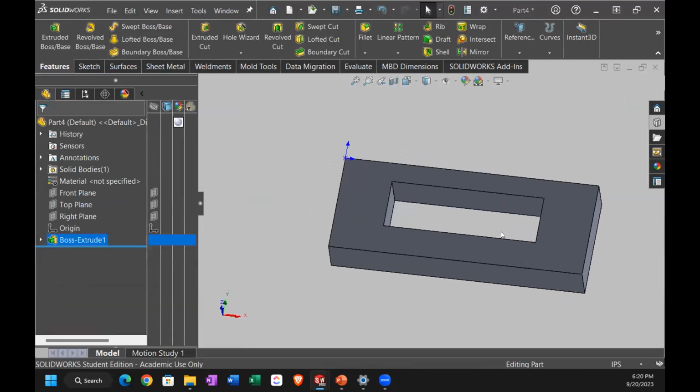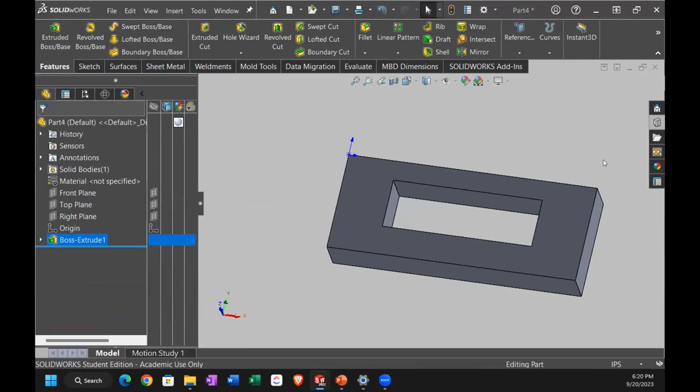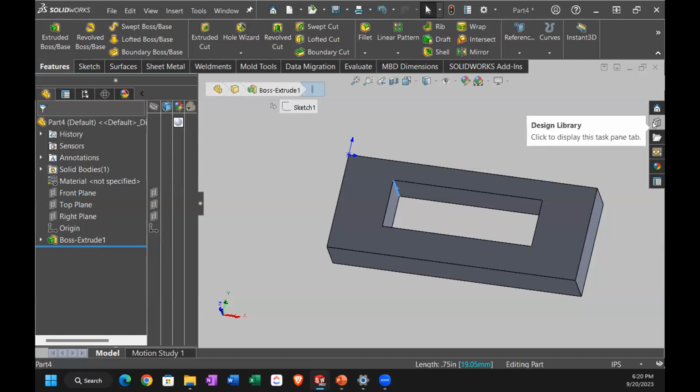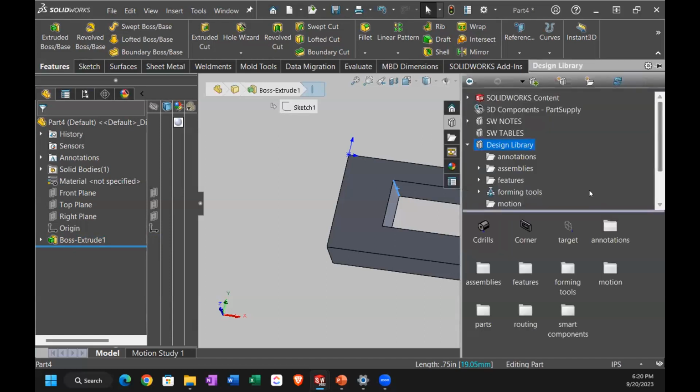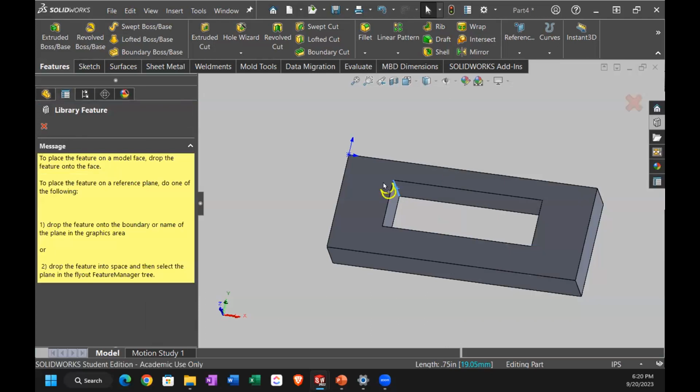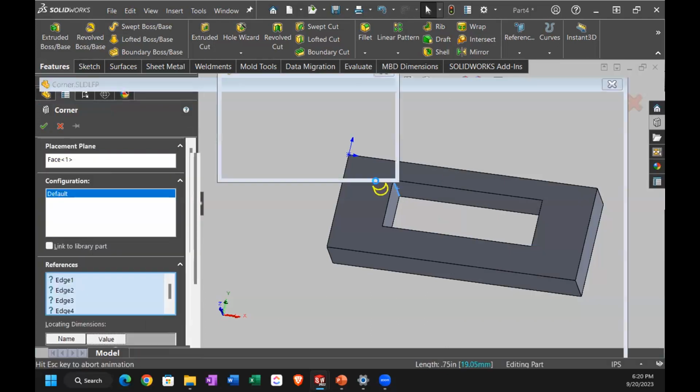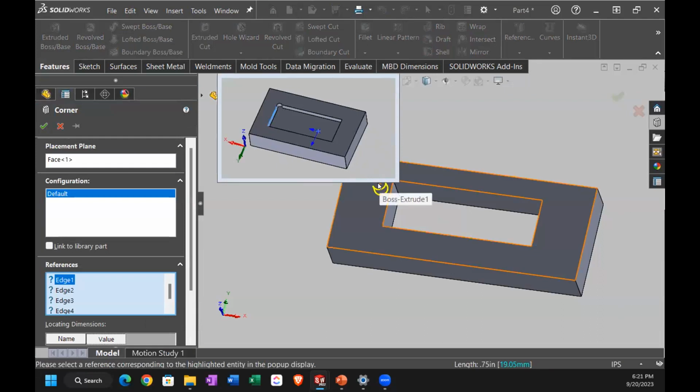So the purpose here then is if we just put a fillet in there, well, I can't put a square peg into the rounded hole. So if I have something that fits in there fairly tight, then I want this corner relief to provide that square shape someplace to go. All right, so that looks like I kind of got it backwards, but I'm not worried yet.